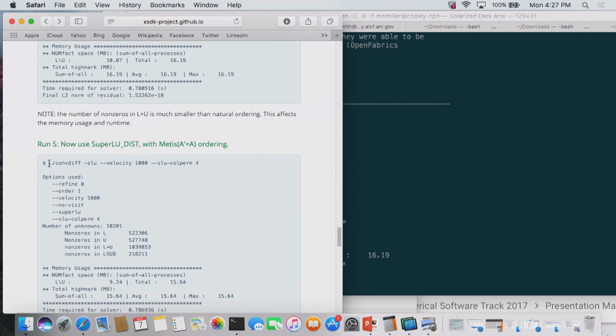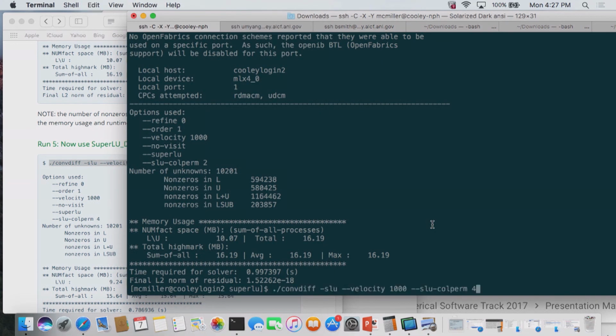So that's another ordering, the graph partitioning type of ordering, METIS. So this is using METIS internally to do this. Right, the option here is still 4, it's using METIS. So we'll rerun that. Now it's improved a little. It's from 10 megabytes to 9 something, and the time is also improved a little.